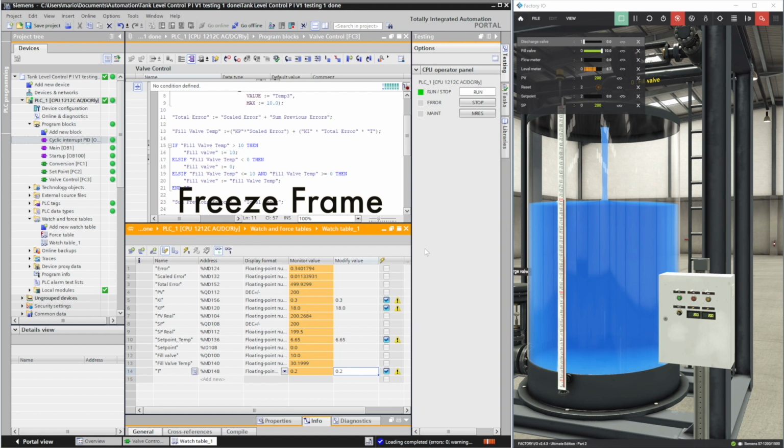This is because we are sampling half as much as before, every 200 milliseconds instead of every 100 milliseconds, which means the total error is calculated less frequently and comes to approximately half of the value it was previously, which was 989 when T was set to 100 milliseconds.